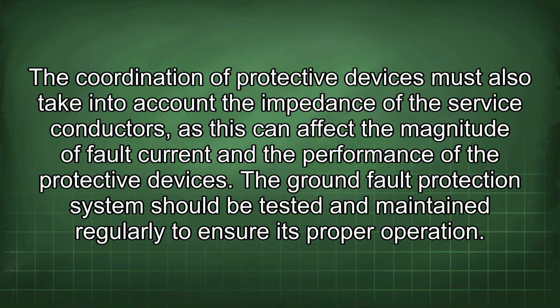The coordination of protective devices must also take into account the impedance of the service conductors, as this can affect the magnitude of fault current and the performance of the protective devices.